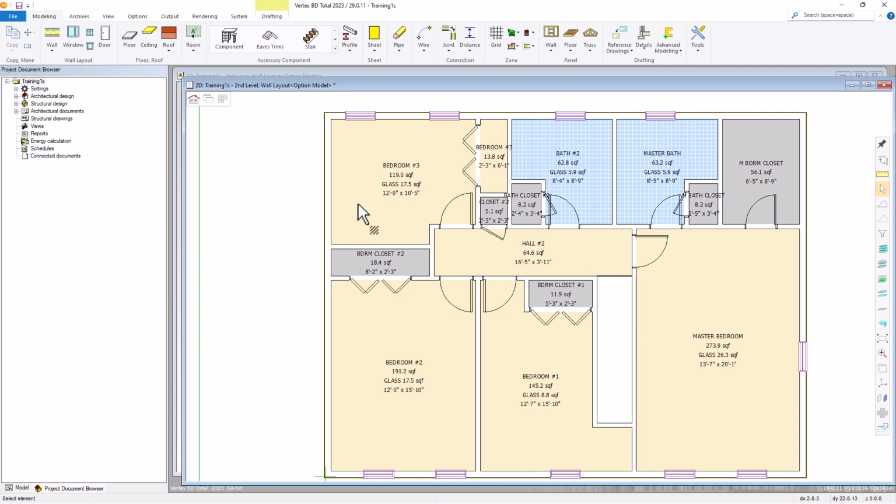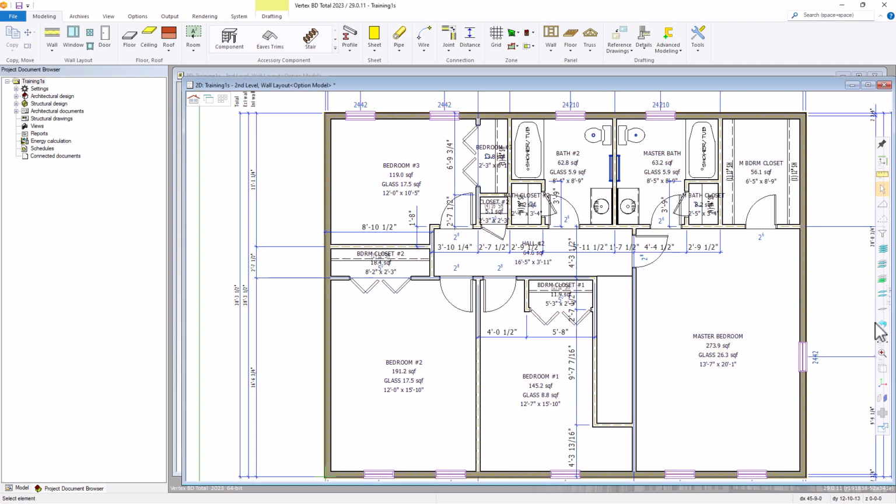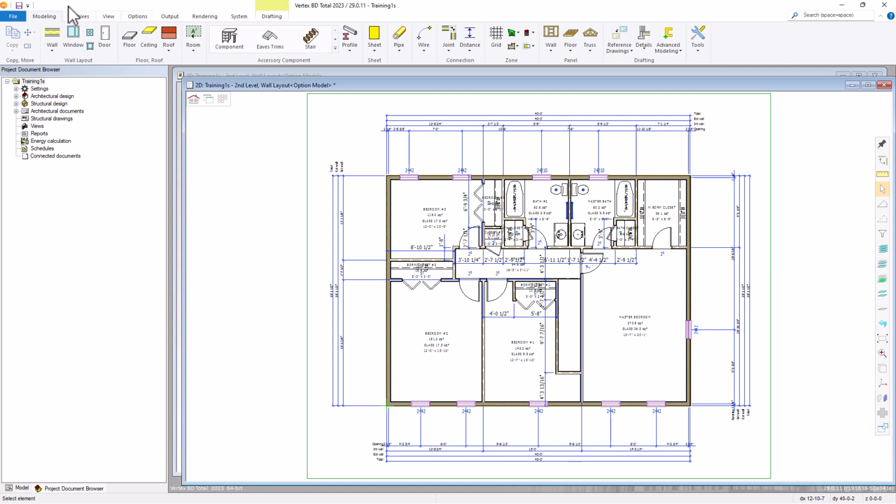Let's turn on our default layers. We'll go over to the toolbar to the blue arrow, which is Restore Default Layers. And again, all our color coding or color fills are turned off, but our labels remain. Hit Shift A to zoom out and hit Save. In the next video, we'll create drawing sets and generate material reports.